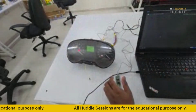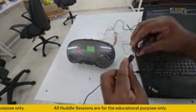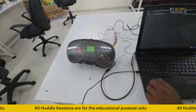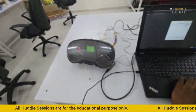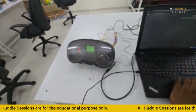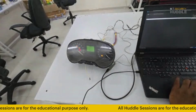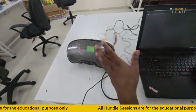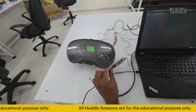So we are using this wire, micro USB to type A USB. I'm connecting over here, and this is going to connect with my laptop. In the laptop, I hope something should be visible over here. If I connect and run ls USB, this is the ls USB where the Microchip emulator demo, the Microchip Technology IC we are using here, shows up. So I want to attack directly. We are doing a fuzzing attack on the entire thing actually. Before that, I need to set up the USB tin in the Linux machine itself.